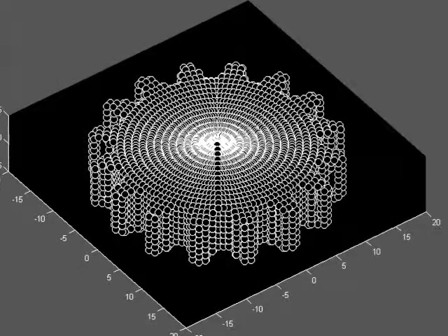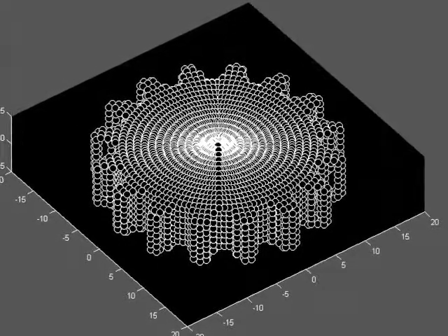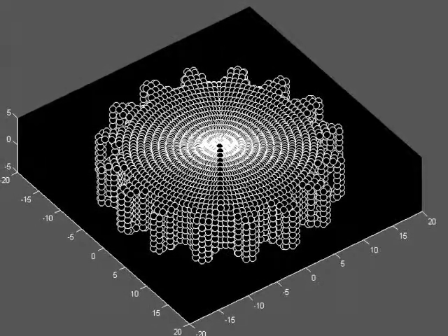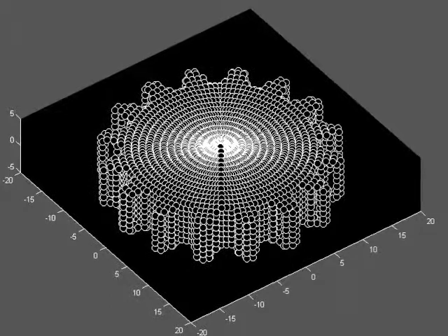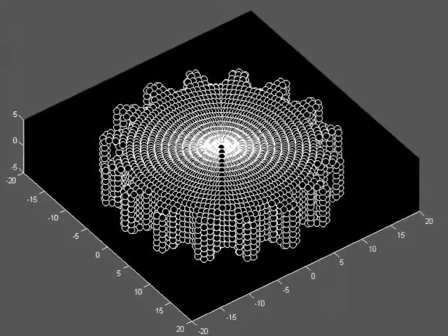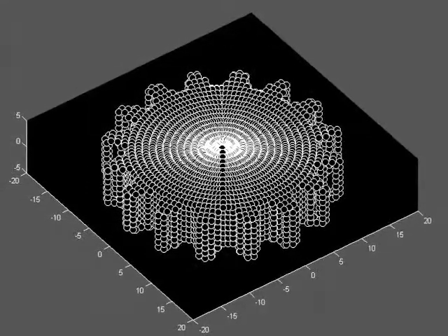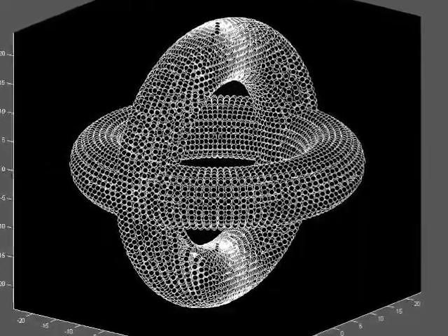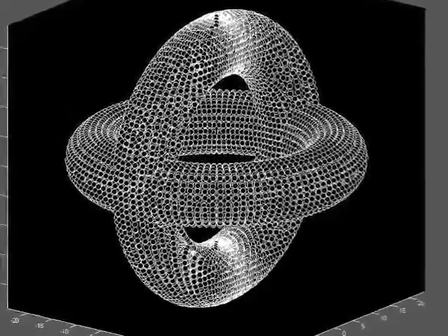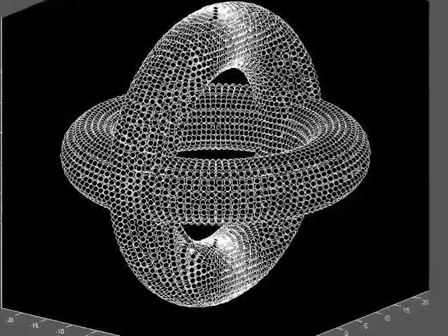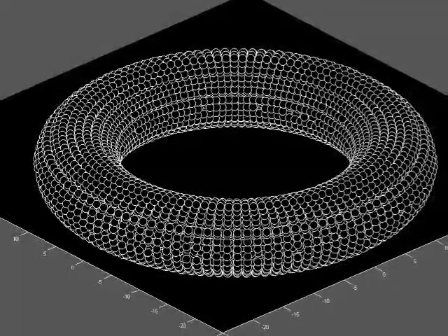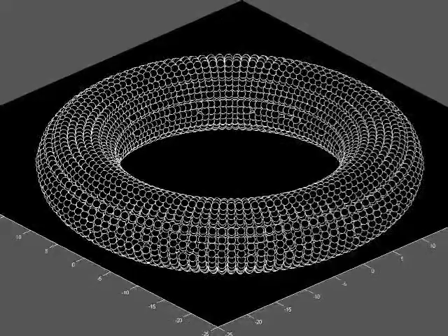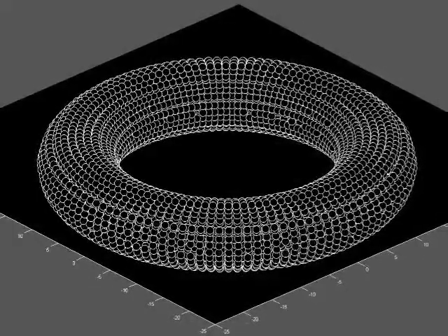Once all the intersections have been determined, they are then outputted in two forms. The first is the form that would be inputted into the display, which consists of 50 characters, either ones or zeros, depending on whether the LEDs are on or off. There are 50 lines per cross-section and 60 cross-sections per model. The second output was a list of intersection points that could be fed into the display program. This program was written in MATLAB, and its purpose is to take the intersection points and plot them in 3D. This allows the user to see what the output would look like without having to upload and run them all on the display. The second objective, writing code for the display, is on hold until a prototype has been developed.